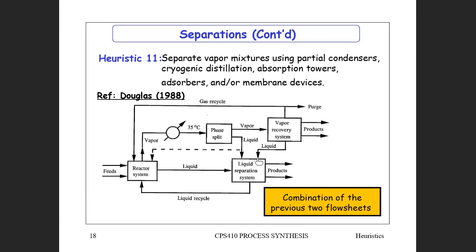That can produce liquid. Let's say you use a partial condenser. Partial condenser means it's at the top of the distillation column. You don't condense the entire vapor stream. If you've got non-condensable vapors like oxygen, nitrogen, argon, carbon monoxide, you would use a partial condenser, and those would come off as a vapor directly off that partial condenser.